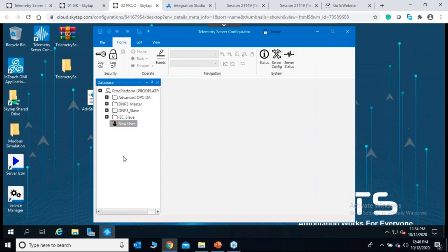Okay. We have another question from Stefan. For DNP3, will incoming socket connections be supported? Connection to be initiated by the field RTU and not the server? Carla, can you please repeat the question? Yes, sure. For DNP3, will incoming socket connections be supported? Connection to be initiated by the field RTU, not the server? Yes, actually, it will support connections, and it shall be initiated by the RTU based on class configurations, if this is what he asked for.